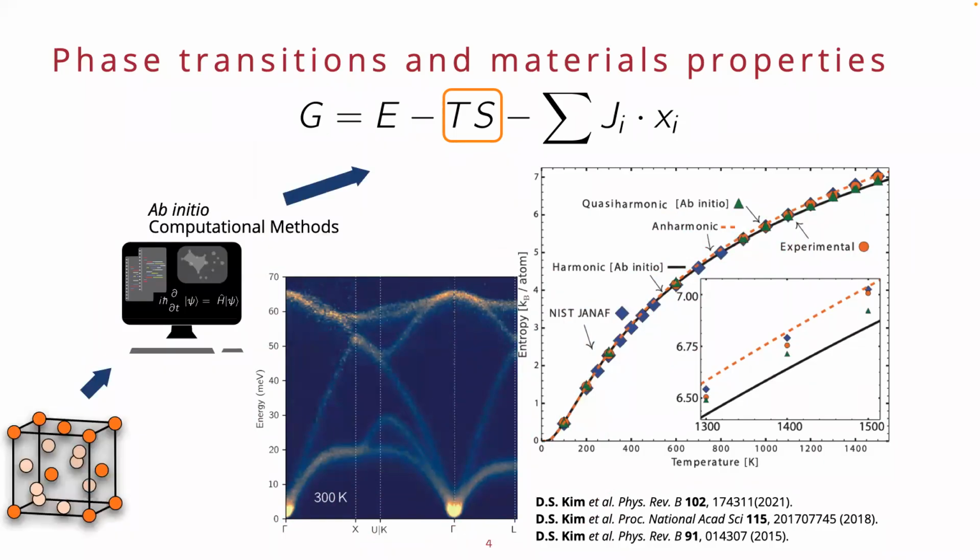But not only that, we can actually compute our entropies simulated, right, in the computer. So this is a simple case where in a bulk system like silicon, you can start from your structure. You can calculate all the components of your free energy and compare them directly to your heat capacity measurements, or use this information to drive understanding of phase transformations or transitions.